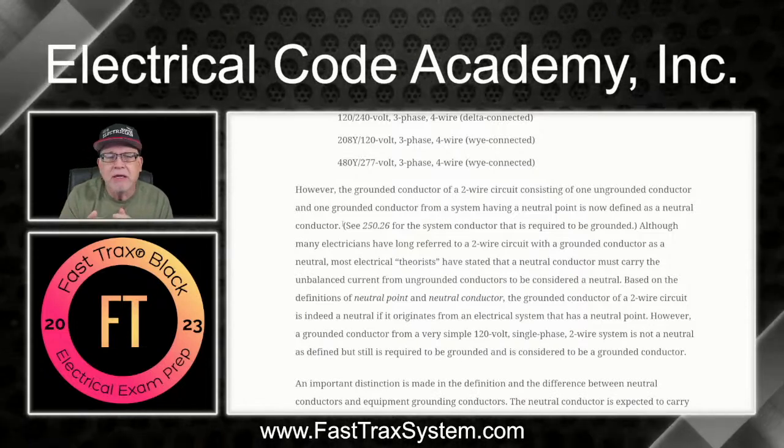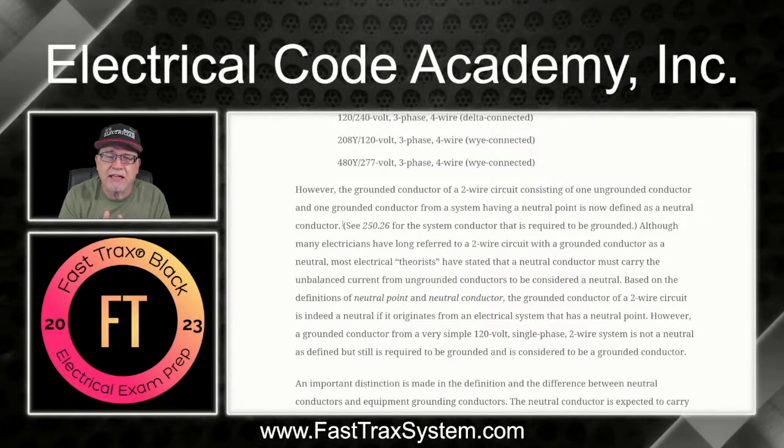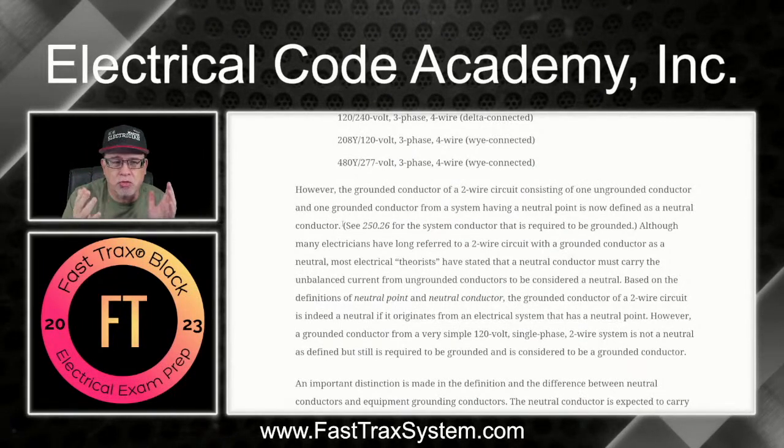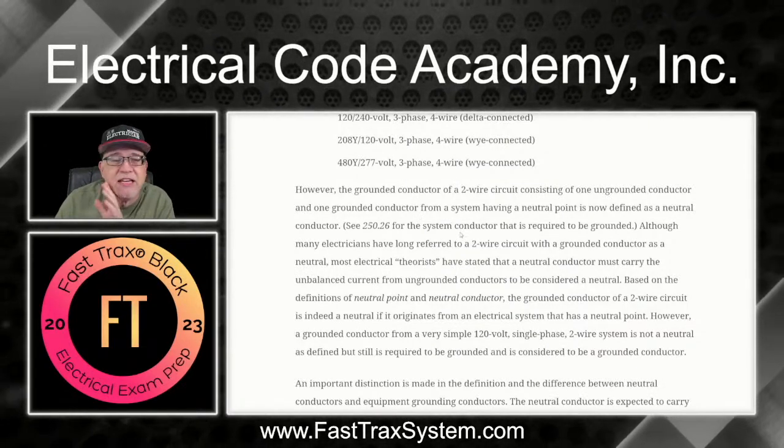That's why I tell you, you can have neutrals that are grounded conductors, but you have grounded conductors that are not necessarily always a neutral. And we'll see that in a second. An example of that will be a corner grounded delta, but let's look at this discussion here, because this is a neat discussion.